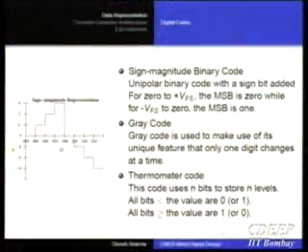It can produce glitches. Okay, on the other hand, gray code will have this advantage that as long as the numbers are changing regularly, only 1 bit will change at a time. But this advantage will be lost if the number is changing randomly. Okay, then you have the same problem. But if, for example, you have a ramp or you are sweeping something and so on, then the gray code can be advantageous because then it will avoid glitches. Okay, so that is one area in which you use gray code.